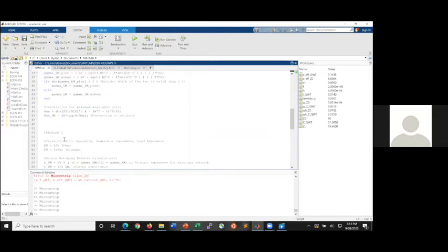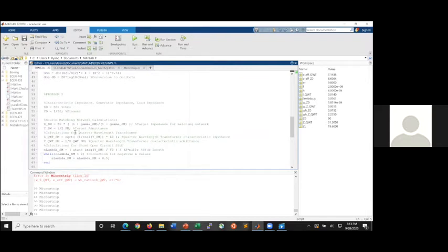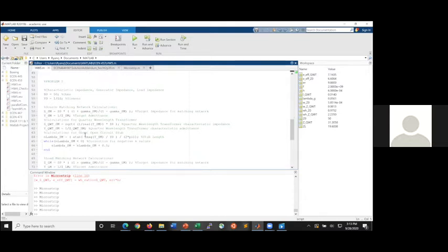And then once I actually go through and want to design, I solve for what I call the target impedance by rearranging the equation, and I turn that into a target admittance. I get a quarter wave transformer equivalent characteristic impedance, and then I also get the stub length. That tells me pretty much what I need to know for the design. So it'll give me the length of the shorted stub. Yeah, it's just plugging in the math. There's no preset design stuff. Okay, that's fine.